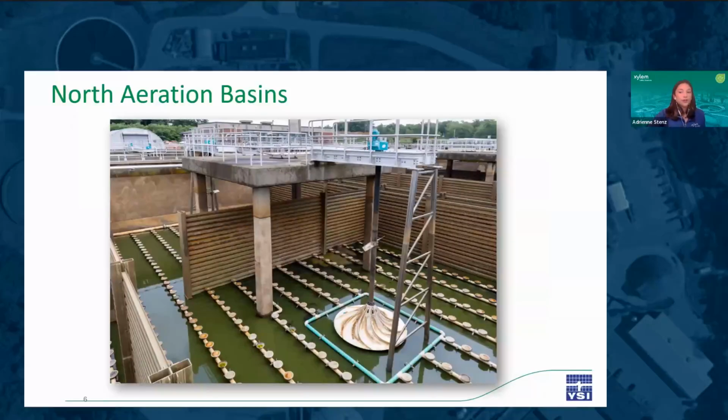North Aeration Basin 1 was drained for the month of June, so here is a cool photo of what that basin looks like while it's drained. This is the post-anoxic zone of the basin, which is outfitted with diffusers and a mixer to operate as a swing zone. There's also baffle walls in this zone to slow the movement of the water. These basins are about 20 feet deep.